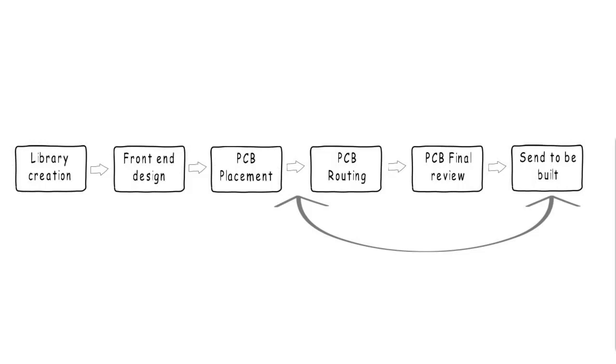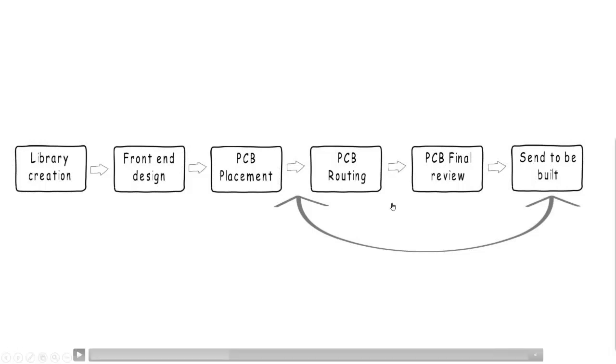And the kind of thing that a lot of CMs don't tell you is a lot of times they won't identify everything that's wrong with that board. They'll do just enough to get a build through. And the next time you send the design through, they might clear up a few more things. They're looking out for themselves in the process of doing DFA analysis. They're not looking out for the customer.